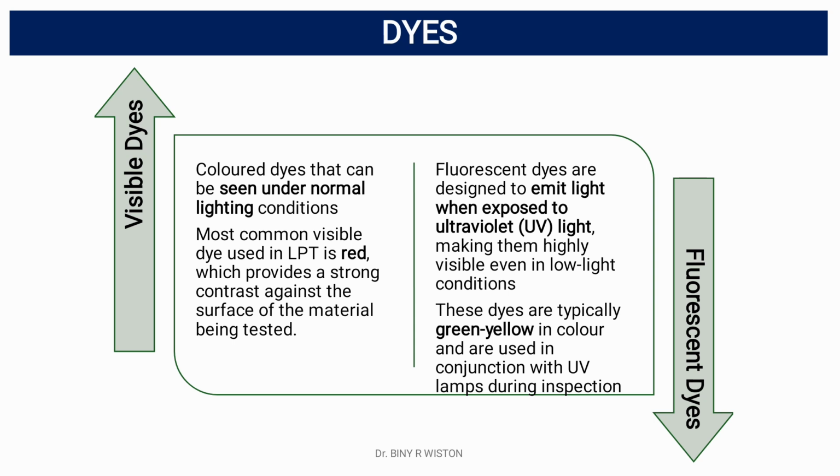Whereas fluorescent dyes are designed to emit light when exposed to ultraviolet light, making them highly visible even in low lighting conditions. These dyes are typically green-yellow in color and are used in conjunction with UV light during inspection. High sensitivity is observed in fluorescent dyes compared to visible dyes, which makes them capable of detecting small defects.